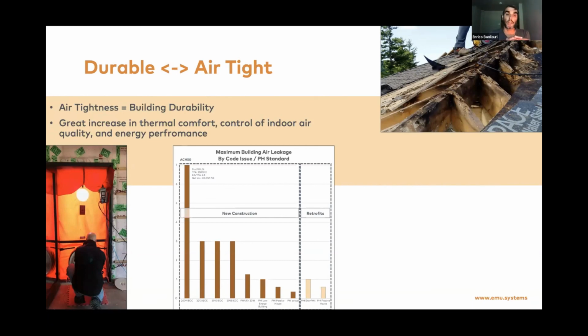From 2012, Energy Code introduced a mandatory blower door test requirement with a cap at 3 ACH 50 air changes per hour. And that has caused a lot of headaches for professionals because that was never a requirement before.